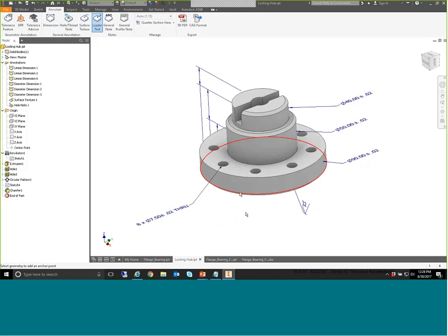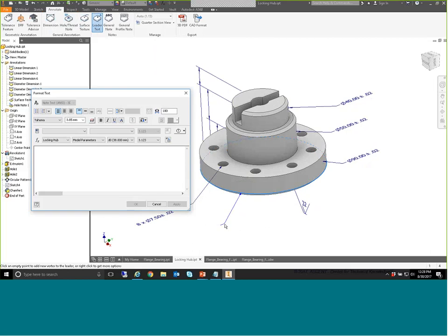So I've just activated the command. I'm going to pick an edge that was chamfered, and I'm just going to enter actual data myself. So I'm going to say there's 3 chamfers in this model, and I'm going to highlight the size of those. Now, from experience in working with this model, I know that that parameter value is D33, and I can set the precision on that parameter, and I can enter it. So it's basically pulling the parameter from the model to identify the size of this chamfer. I'm going to add that twice because it was a D by D chamfer.